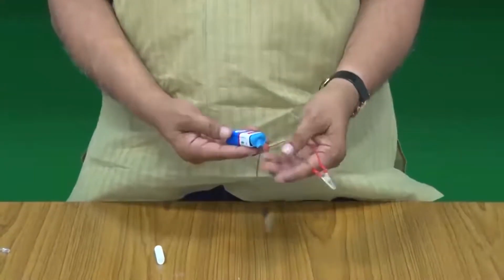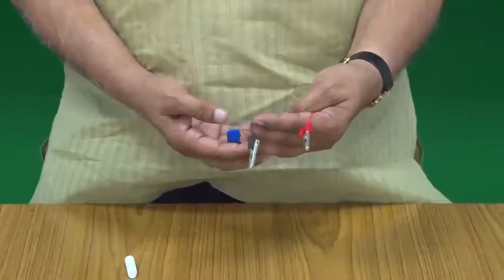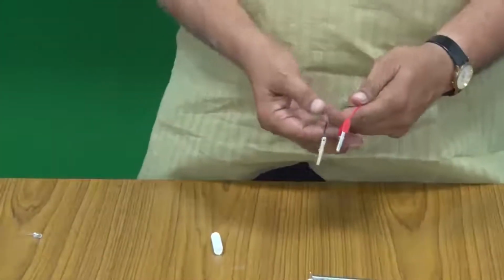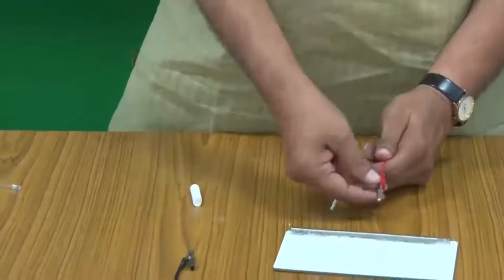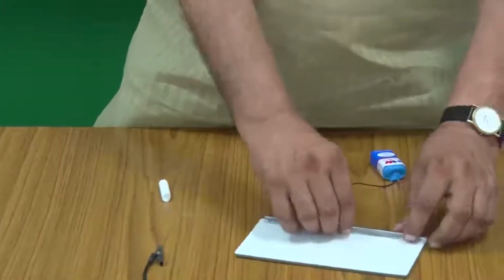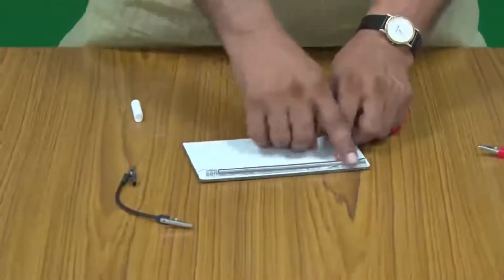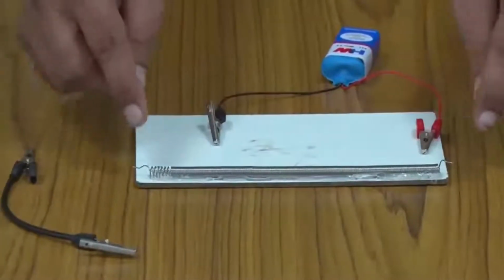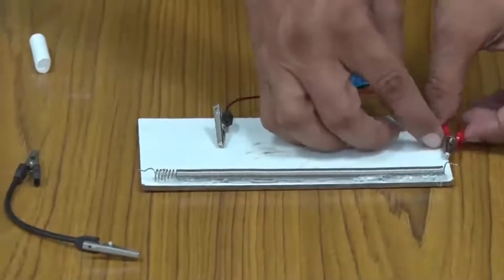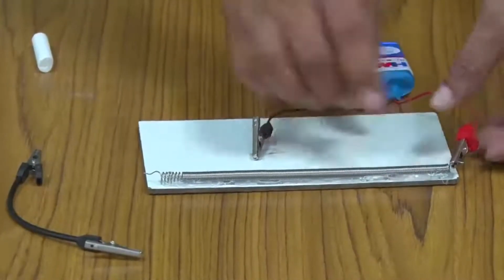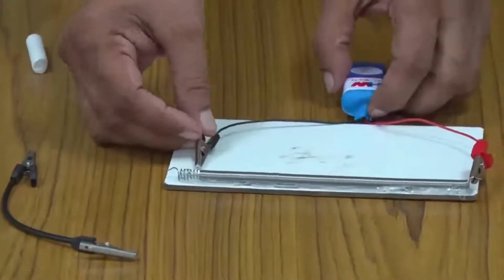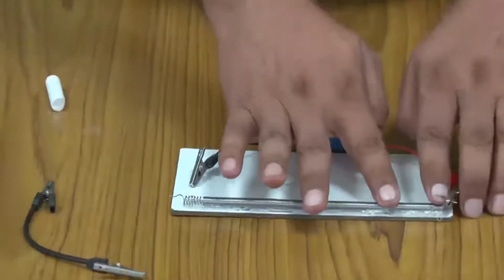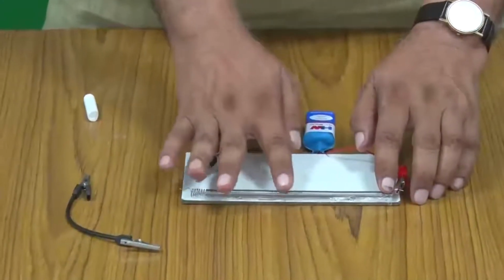So, I have this 9 volt battery, but I cannot give this 9 volt on the LED, it will just blow. I will talk about that a little bit. So, what I am doing is I have taken this wire, this is a heater coil, and I will connect this battery at the ends of these two wires. One I am connecting and one I will connect when needed. So, this whole 9 volt is dropped on this, and then I can take part of it, smaller voltages I can take from here.